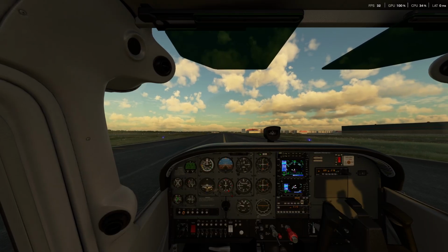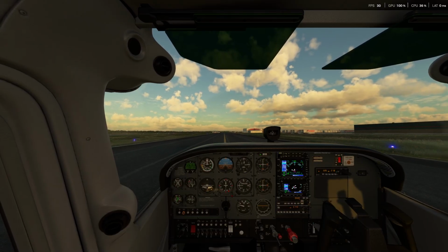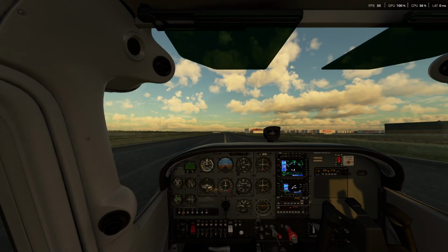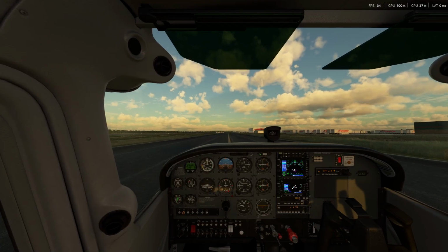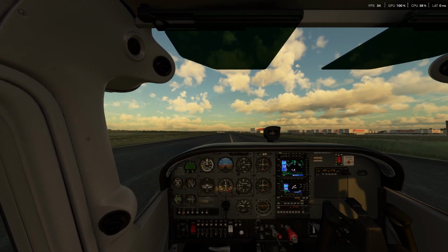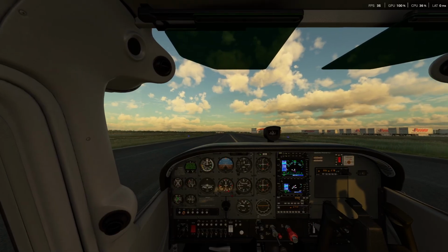In the event of an emergency affecting the safety of flight during the takeoff roll, I'm going to reduce the power to idle and stop straight ahead. If airborne with enough runway remaining, I'll maintain control and land straight ahead.